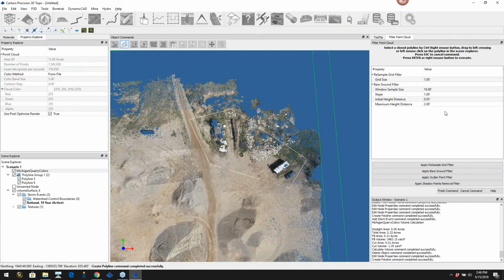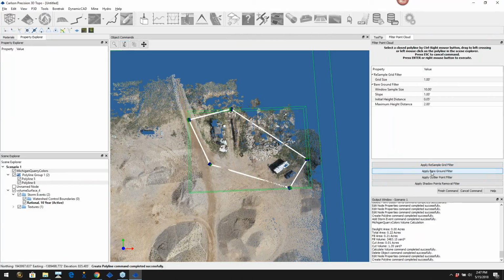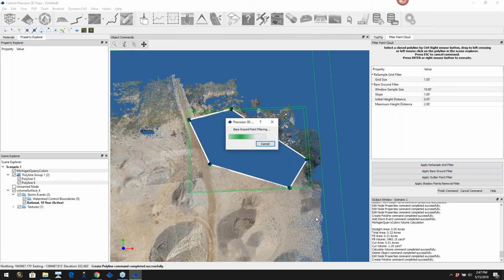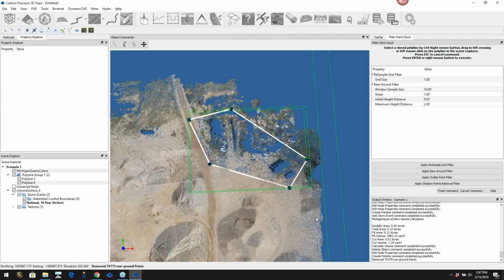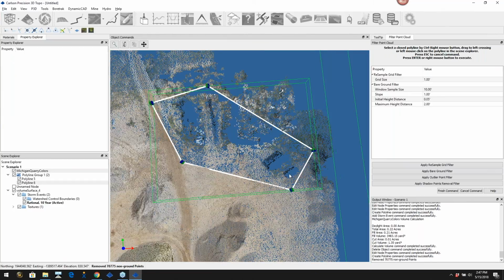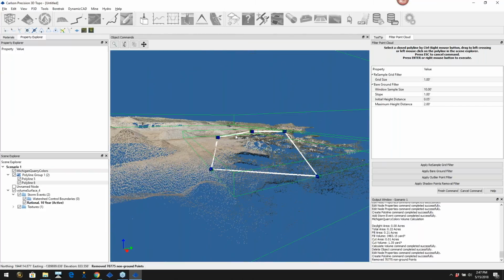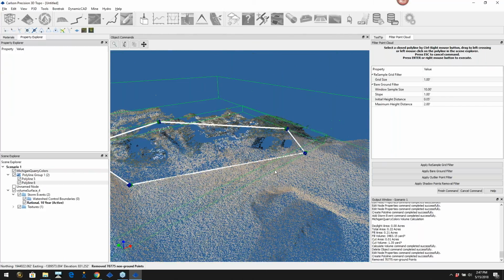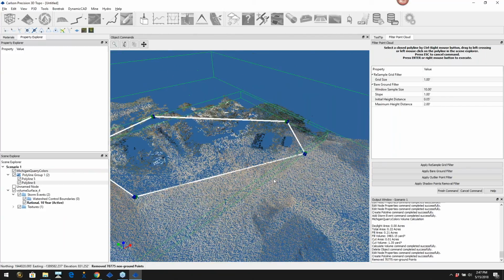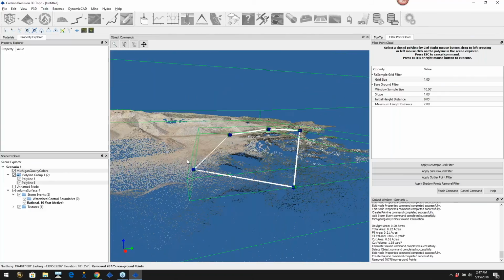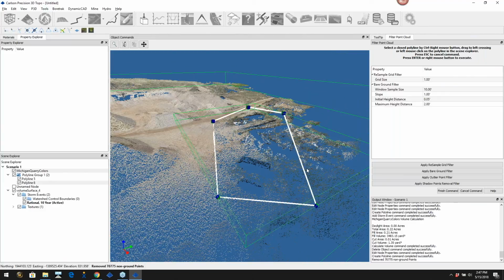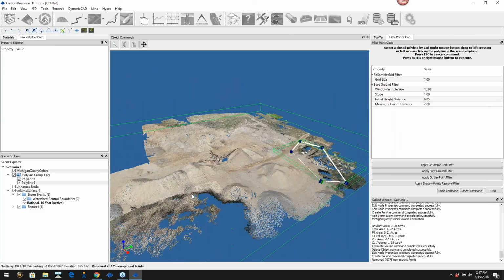And for each one of these volume surfaces or finished surface topo models that you create in here, you can save them. You can export them out as a LandXML surface file or a Carlson TIN file or a TopCon or Trimble surface file as well. You can also import all of those kinds of surface files in here, because the neat thing about P3D Topo is once you create the surface model, we have a huge selection of surface editing tools.